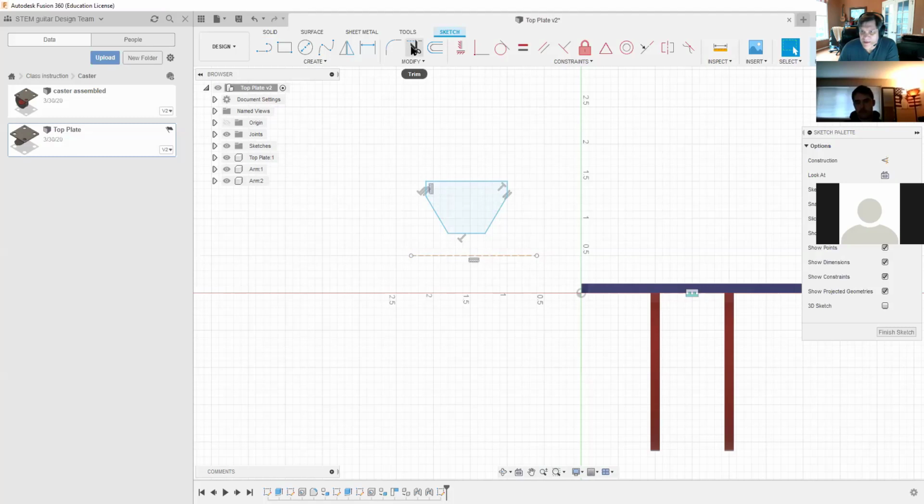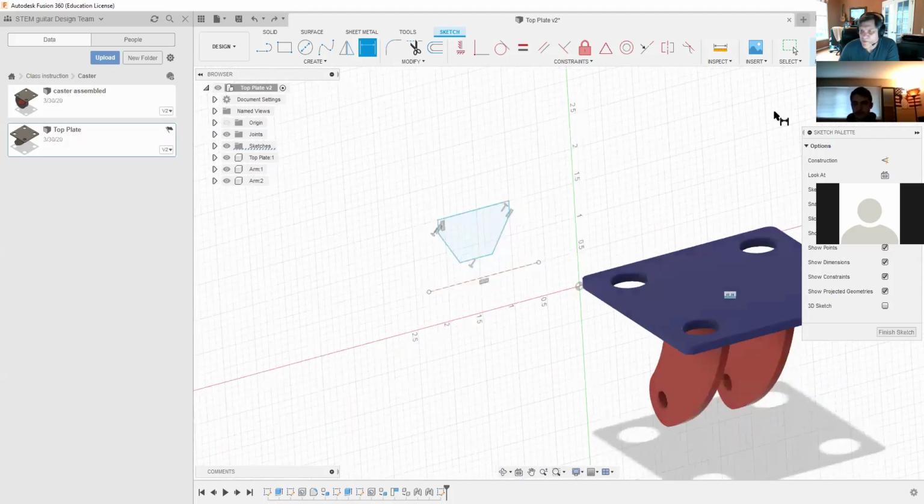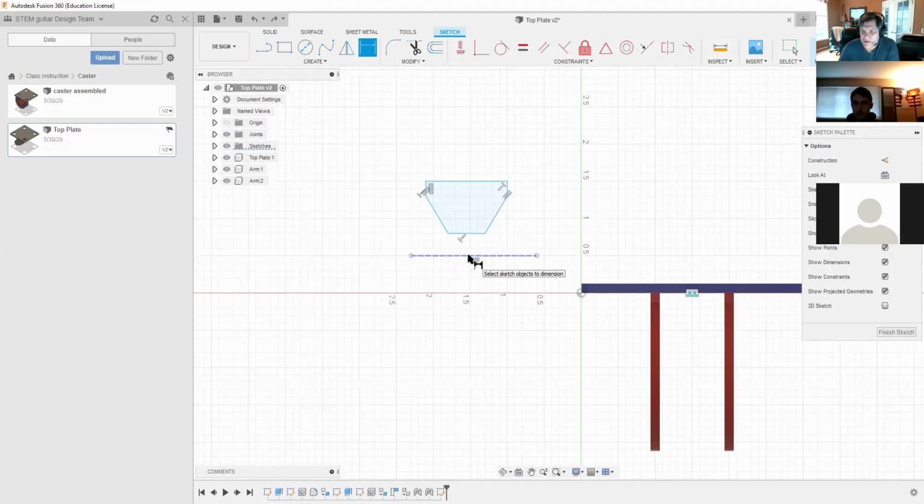So we know that the diameter of the hole, I just cut those, undo. All right. The diameter of the hole, let me go ahead and tilt this just a little bit. So the diameter of the shaft hole is 1/4 inch. So the distance from the center line to the bottom of the object needs to be 1/8 of an inch. Why is that?